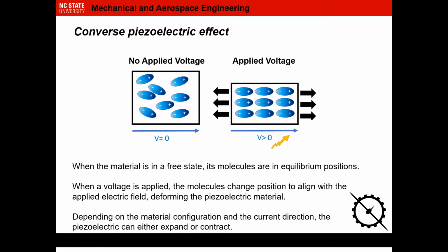There's another phenomenon known as the converse piezoelectric effect that also applies to piezoelectric devices. It's essentially the reverse of the piezoelectric effect. With the converse effect, when a voltage is applied, the molecules change position to align with the applied electrical field. This deforms the piezoelectric material.